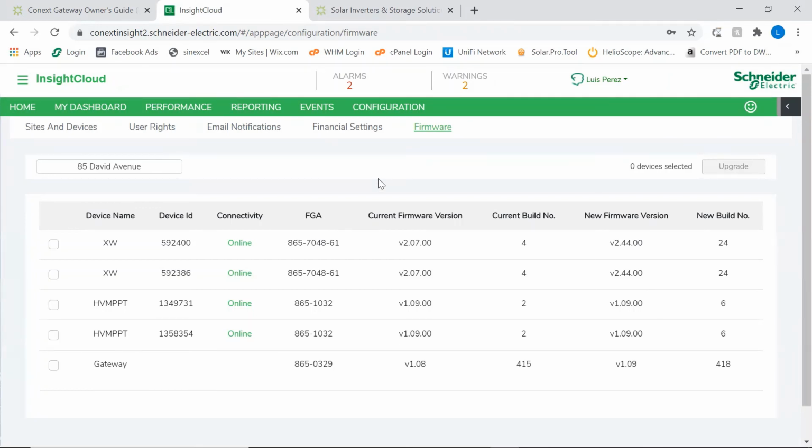If you have a very high-end installation, you might want to allocate for a very small online UPS to be connected to the gateway and to the internet supply in the system, in such a way that during the period of updating this firmware, 10, 15 minutes, you can keep both of them powered up.